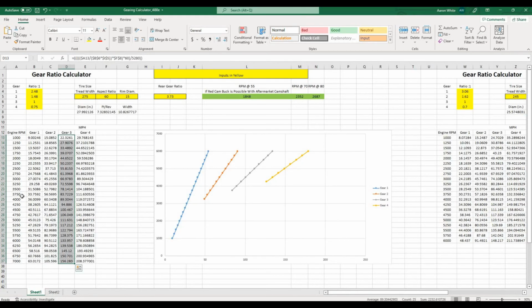So I'm at wide open throttle. I've jumped to 4,000 RPM because I have a 4,000 RPM converter, and I'm running up through my gear. And let's say at about 6,000 RPM, I want this thing to grab a gear. Say 5,500. There's that 122 that we picked earlier. So at 5,500 RPM, I want it to lock the converter up. It's going to drag the thing down a little bit and then just keep right on digging.